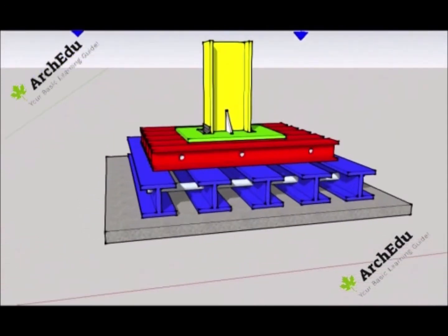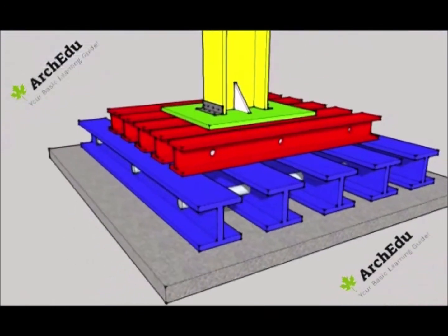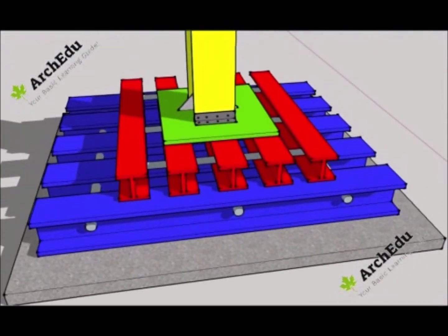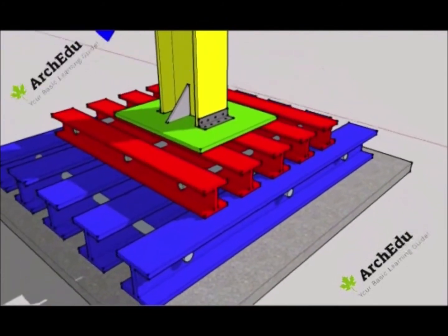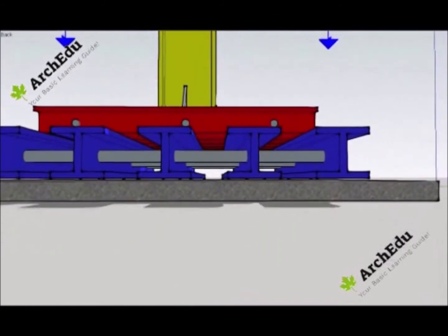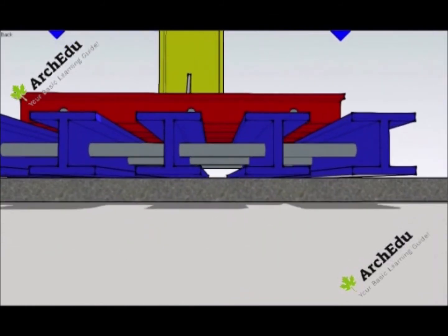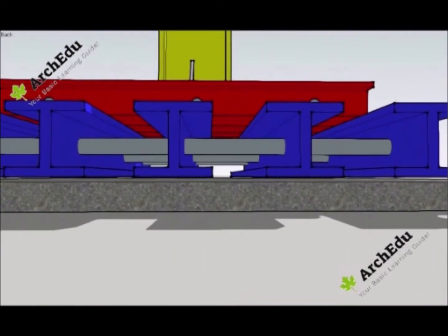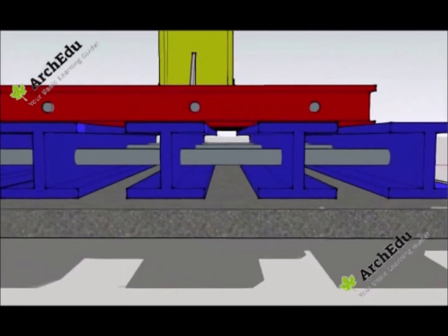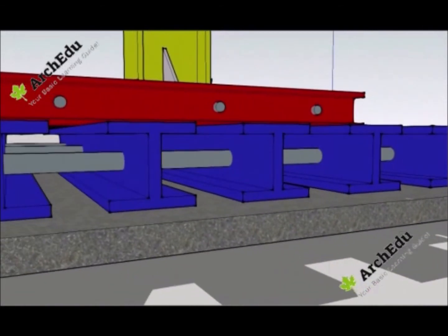Here you can see the rod placed between the sections, those are called spacer rods. Here you can see the steel column is fixed with the base by metal cleats and gusset plates. This view can give you a clear idea about the fixing details. This is how the entire assembly looks. The base plate is generally 10 mm to 20 mm and cleats are either welded or bolted to it.